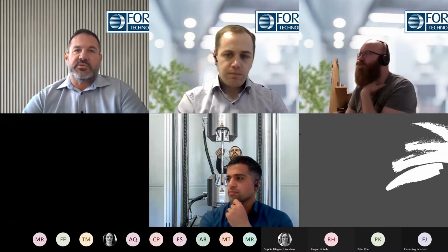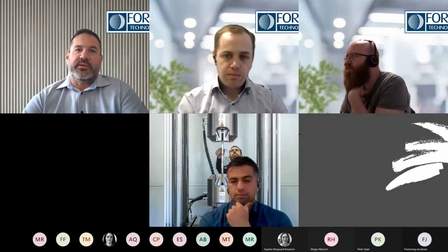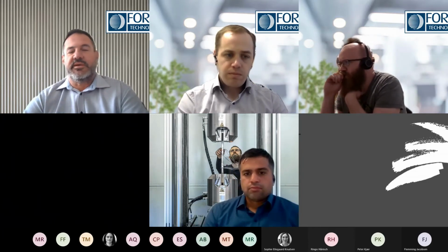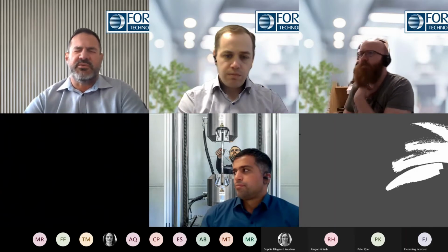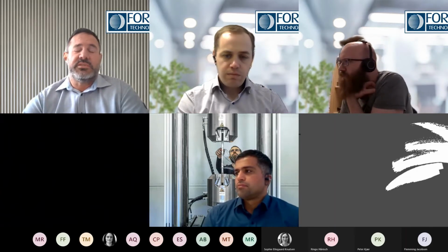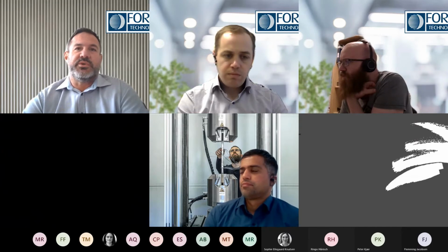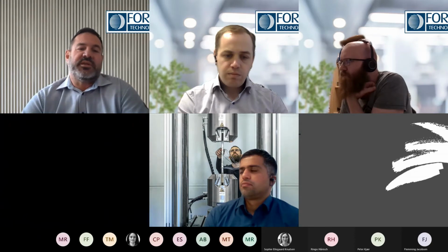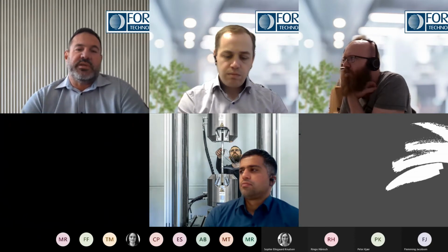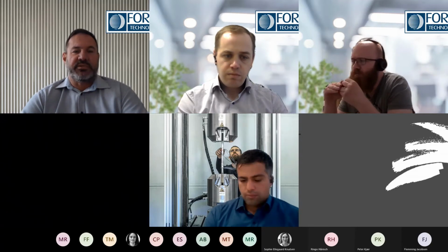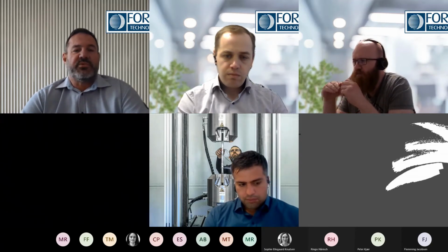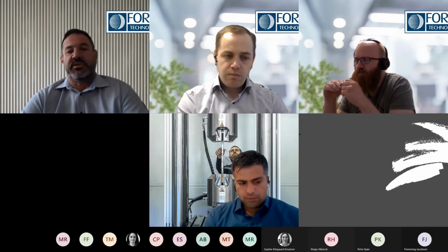Yes, I would say it does, because it depends on the test. Mads, help me if I say something wrong here. If we want to simplify it, we don't want to introduce something at an angle, because then the application of the loads may not be symmetrical. So from that perspective, it's important that it is 90 degrees. Of course, there will be exceptions depending on the geometry of the specimen and what we want to achieve.